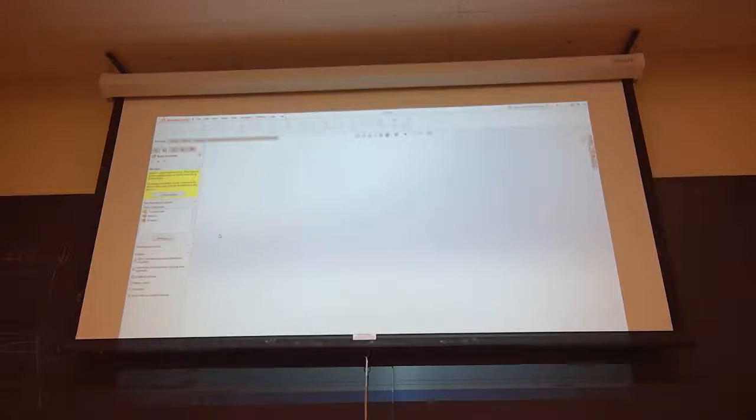I should talk a little bit about this part of the SolidWorks or 3D modeling phase. You have parts that you build individually, but then you need to put them together, right? For example, if you're building a car engine, you're not just going to build it as one whole piece. That's for a couple reasons. One, it's really confusing, really hard, and two, you want to be able to interchange things with ease. So say you move to a different type of material, instead of changing, I mean, you can't even do that. So that's why we have assemblies, which are just separate parts put together.